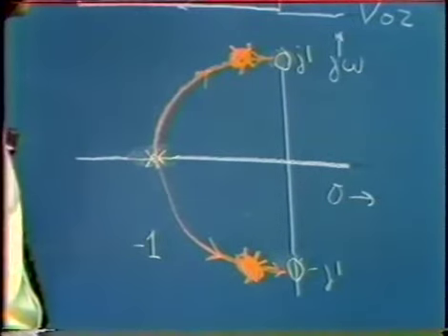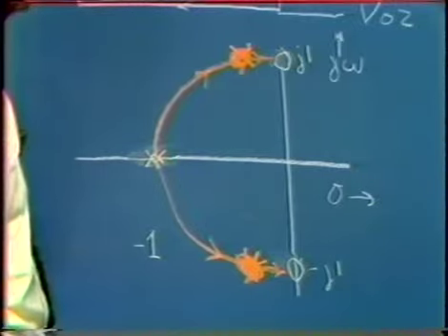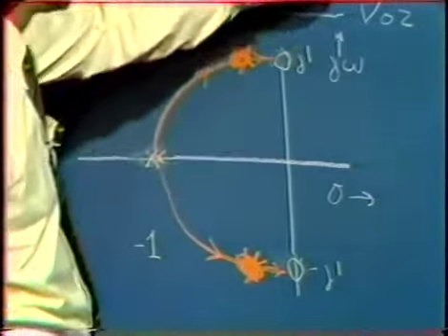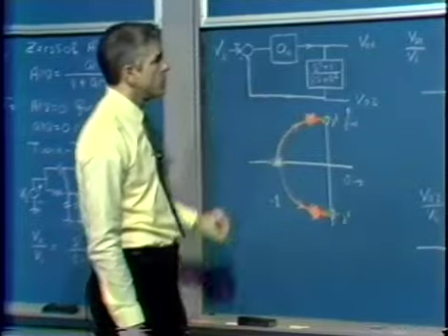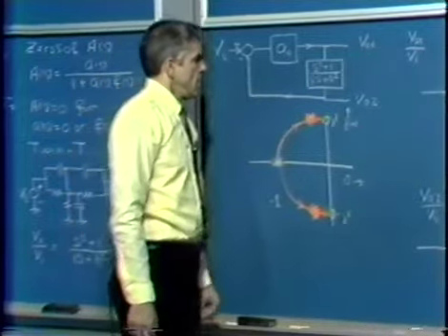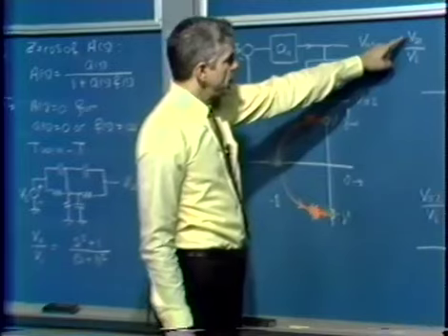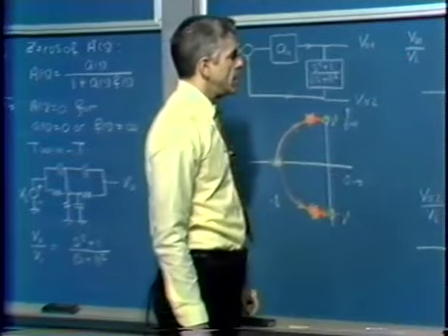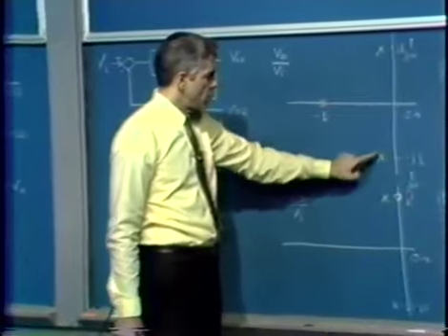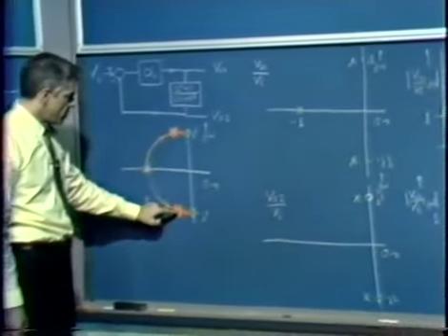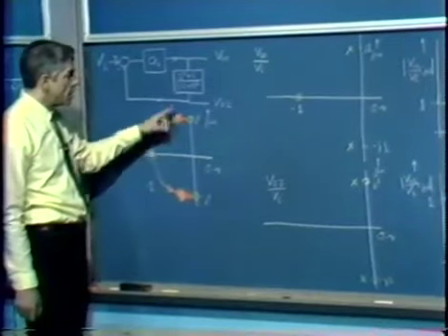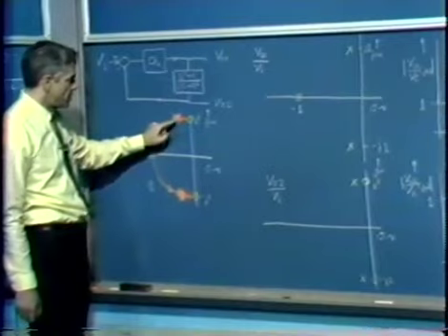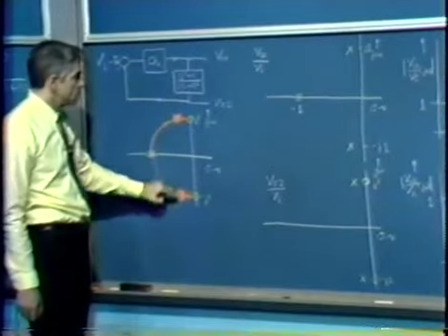And then we consider the overall system transfer function, both poles and zeros, for the two transfer functions, either V out 1 over VI or V out 2 over VI. In the case of the transfer function V out 1 over VI, the closed loop poles are, of course, those given by the earlier development. We've cranked up A naught to this point. The closed loop system poles lie here. They're independent of which output we consider. They're a fundamental property of the system. And so our closed loop poles lie here.